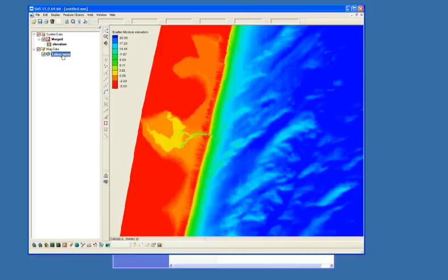So the first thing for building telescoping grids that I would do is, you can do them in any order, but normally I build the domain that I'm going to be using. That would be done with the grid frame. And you would click a point and you see that it anchors at that spot. Then you can extend that inland until where you want it to stop, and then have another click at the end to build the rectangle. So it's hard to see that.